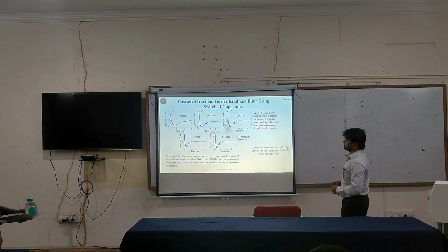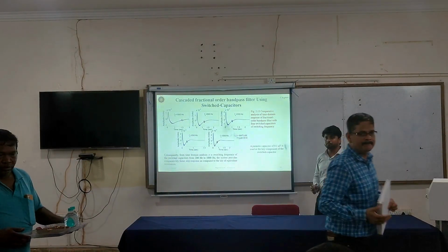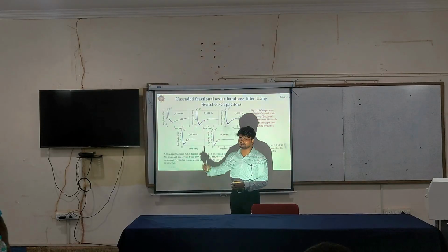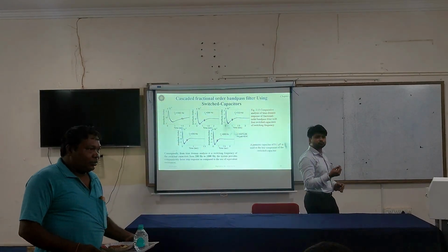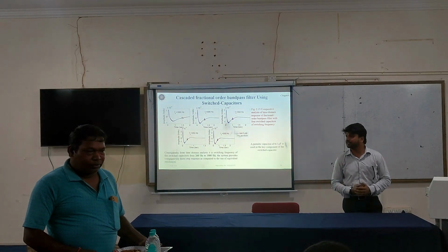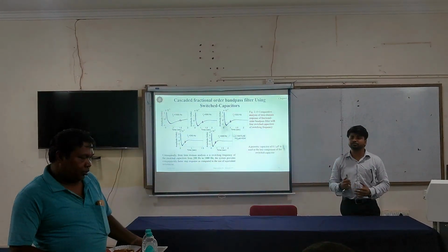The switch capacitor-based fractional-order filter has been carried out at simulation level both in MATLAB as well as in LabVIEW with a very negligible error, because these two software use two different kinds of methodology. In the case of LabVIEW, we are using the power of the transfer function, but in the case of MATLAB, we are using an approximated fractional capacitor in a ladder network.